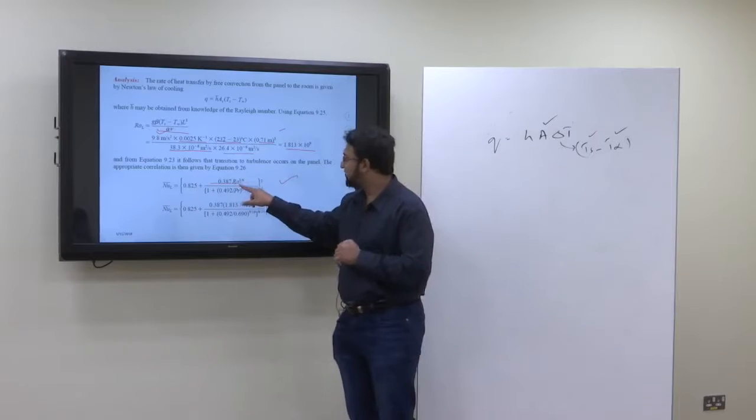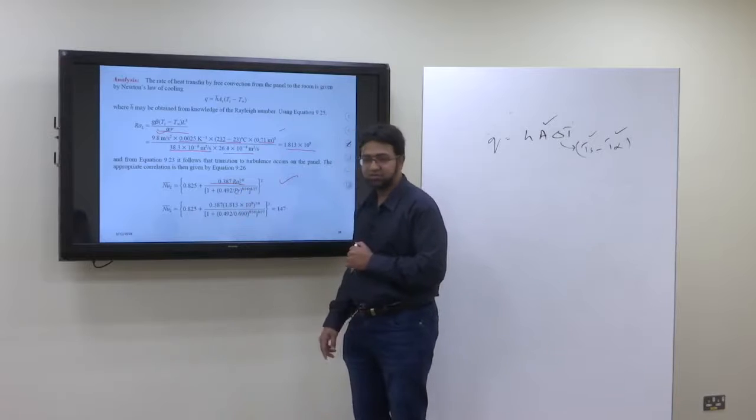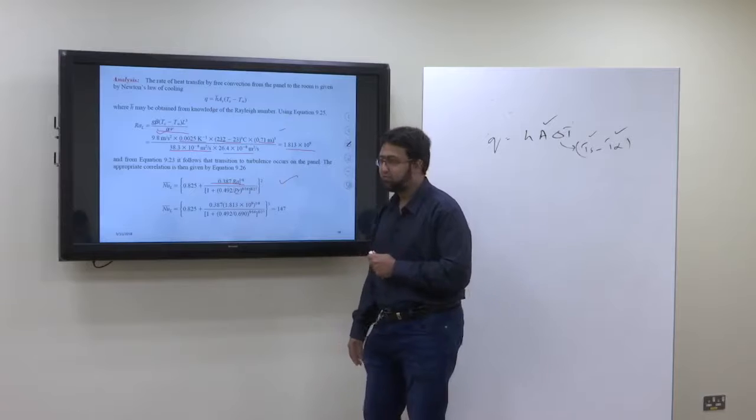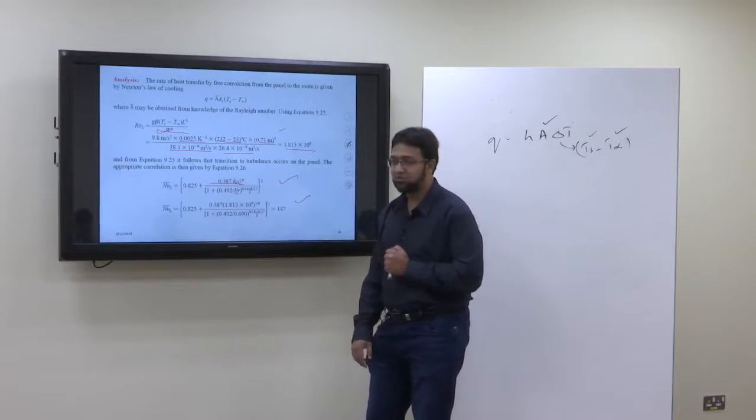It just uses the Rayleigh number. You already know the Rayleigh number, you already know the Prandtl number, and that's it. All the rest are just numbers. Substitute values and find out the Nusselt number. So the Nusselt number comes out to be 147. What's the unit?